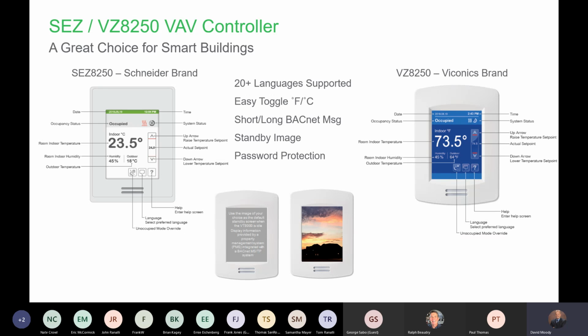But if you're familiar with a room controller or not, there are, I think we're at 12 different types of HMI displays. And this would be a human machine interface, right, for you to look at. You can configure the screen up to 12 different variations, which at the end of the day just means that some of these buttons are displayed or not displayed, or values are displayed or not displayed on the screen, right? So you have that flexibility.